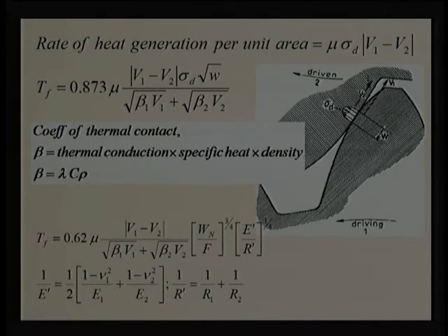Reduction of the temperature by half is significant. Actually, we should point out there should be more and more lubricant additives to at least maintain boundary lubrication, and there should be some carrier fluid which can carry these boundary additives and try to keep some separation, which will give a lesser coefficient of friction.